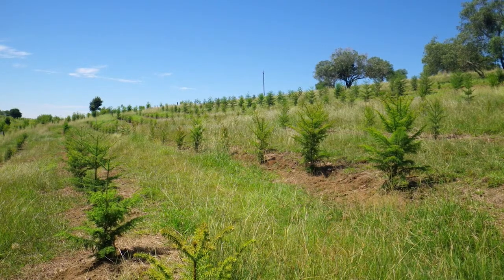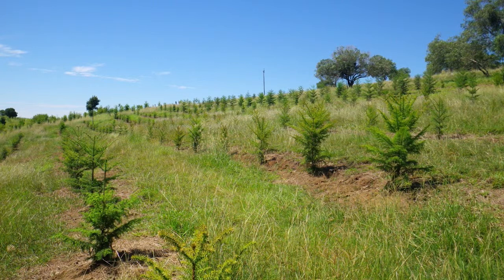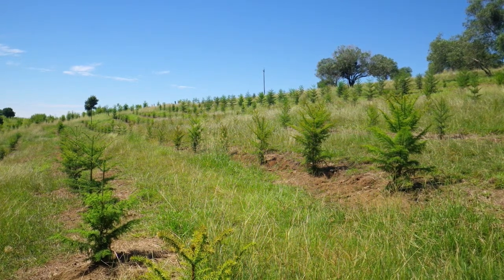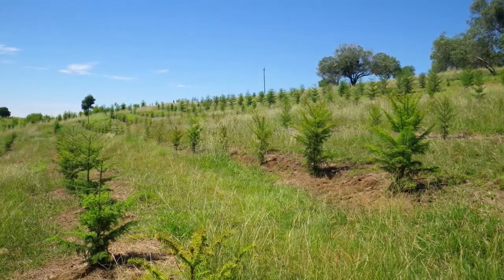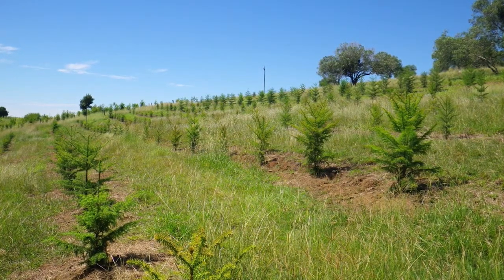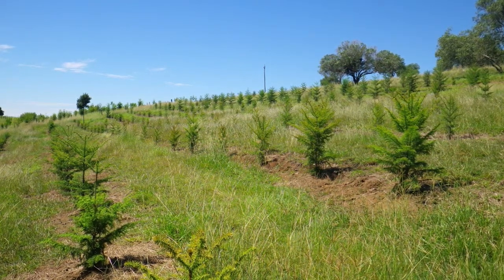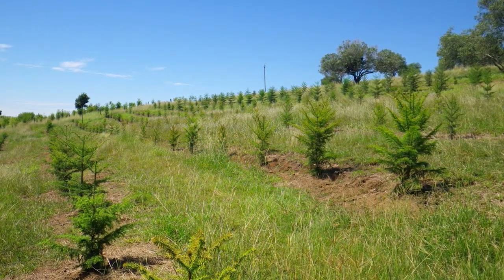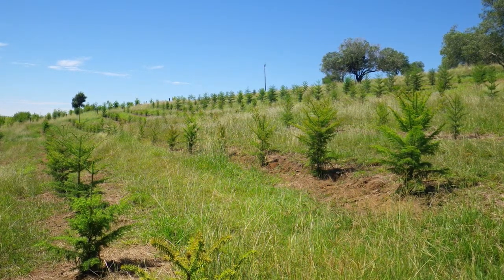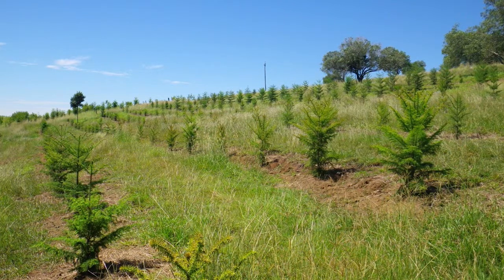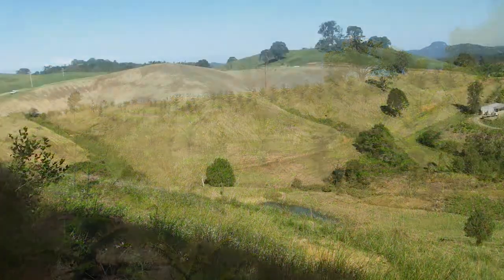Traditional forms of plantation cultivation involved a continuous rip line formed with a ripper on the back of a dozer or tractor. Continuous rip lines were established along the contour to prevent excessive erosion caused by surface water running along the rip line. Even when carried out on the contour, continuous rip lines act like dams, capturing water which will eventually break through the rip, causing erosion. The key to successful cultivation is to avoid controlling water wherever possible.